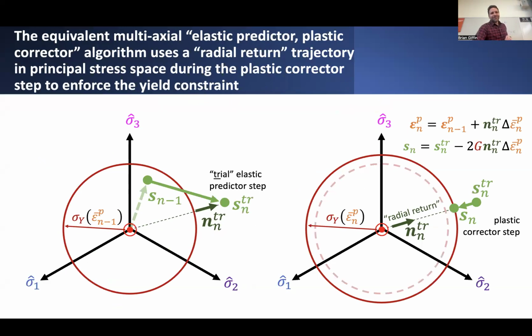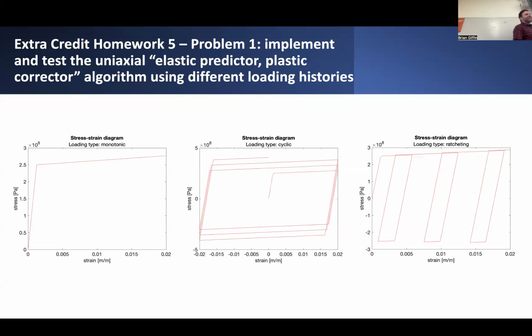And at the end, you run a small script to verify, did I do it correctly? You can run this script to visualize the stress strain behavior of some material model subjected to some history of strain. The input to this function is a time variation of strain that might vary as a function of time. And the simplest possible strain history you might consider is simply monotonic loading. Or in other words, take some function of strain that is linearly increasing with respect to time.